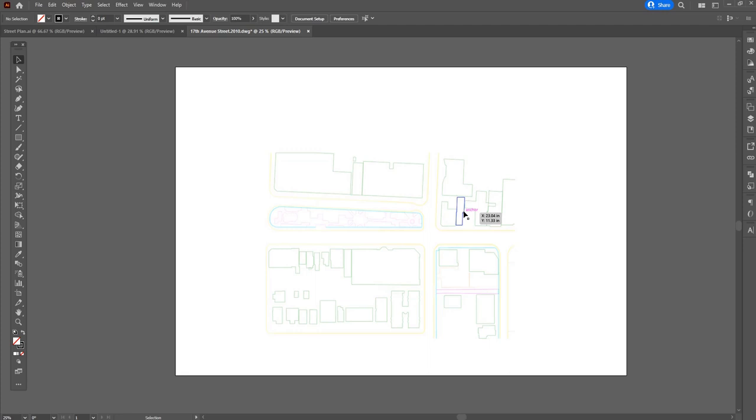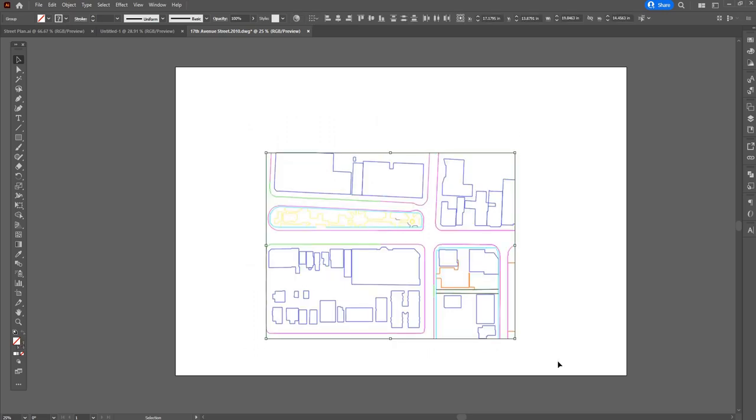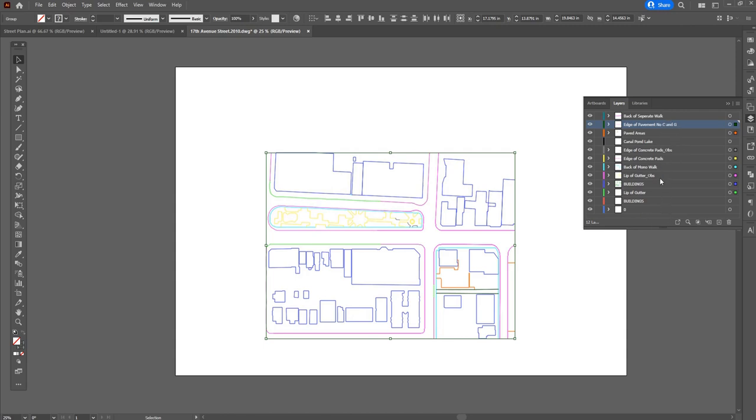Now I'm going to personally recommend this next step for housekeeping reasons and to keep everything on one layer, as these are all the lines and pieces of line work that we're going to be working with on this step. We're going to left click and hold, drag a selection box over all of this content and release. And then we're going to hit Control C. Now we're going to move over to the layer icon over on the right side here. Let's left click. We can say we've got all the layers that just got imported from AutoCAD.